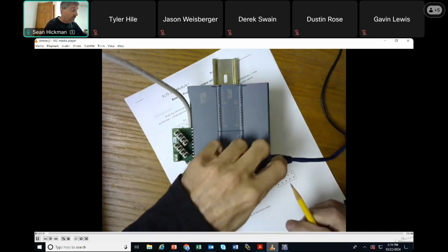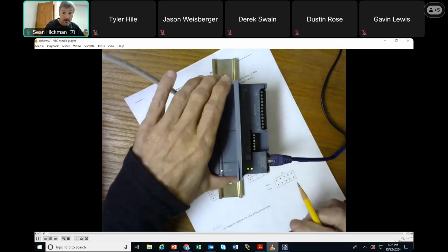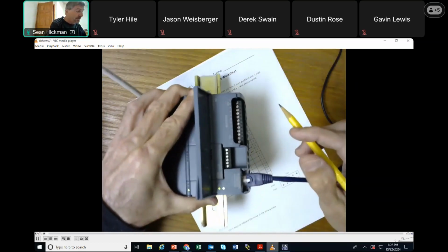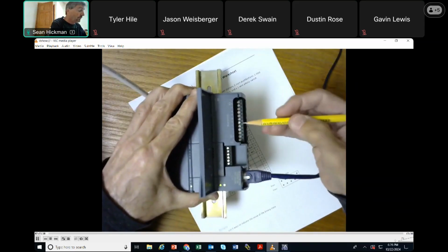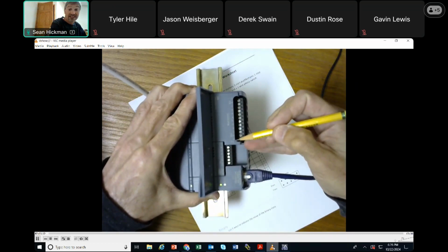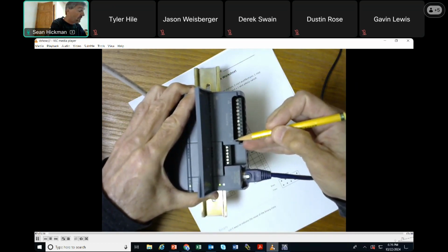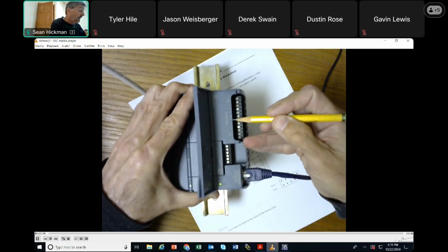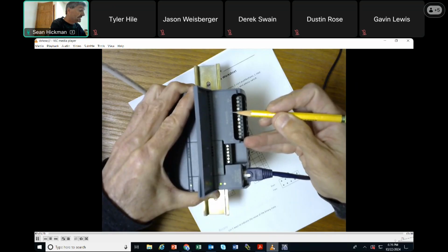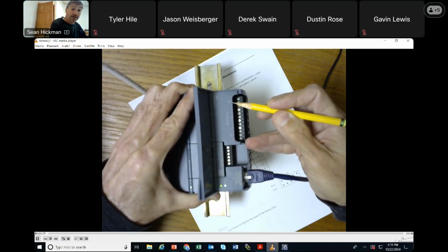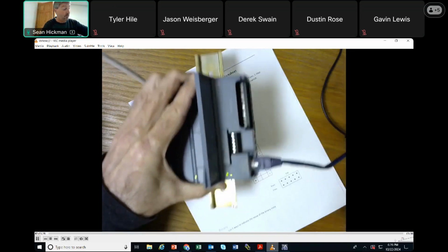Now, what's kind of confusing here is when I look at my relay outputs, I don't know if I can get this quite good enough, but you'll have to take a look at it and I'll draw it for you. This says 1L. That means your line. This says 2L, but it's got 0.0, 0.1, 0.2, 0.3, 0.4, and then 0.5, 0.6, 0.7, and then it starts over at 0.0, 0.1. Okay, what does that mean? Well, here's what that means.